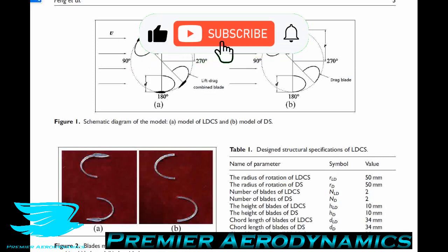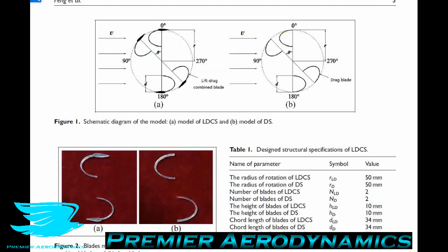Interestingly, I expect that when the blades rotate enough, the resulting pitch angles of the airfoils will be large enough to cause stall. For example here, the effective angle of attack is maybe 45 degrees. That is probably enough to get the airfoil to stall. So this renders the airfoils largely stalled, and that means these airfoils are really just producing drag. So it's additional drag that we have produced as well.